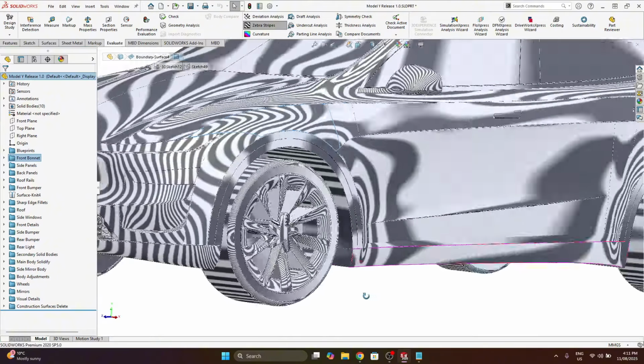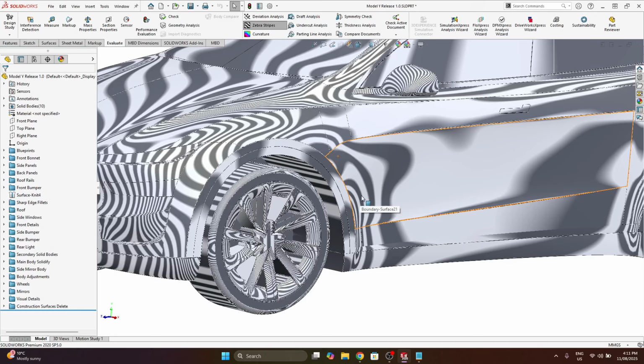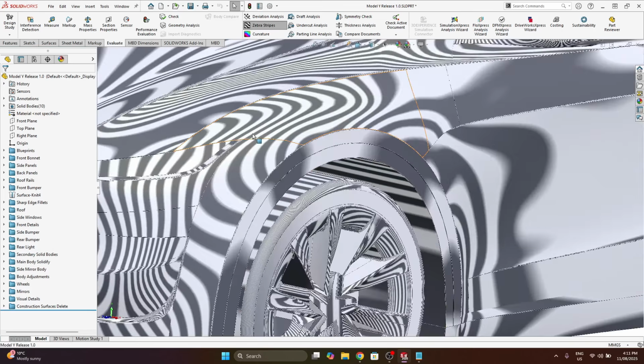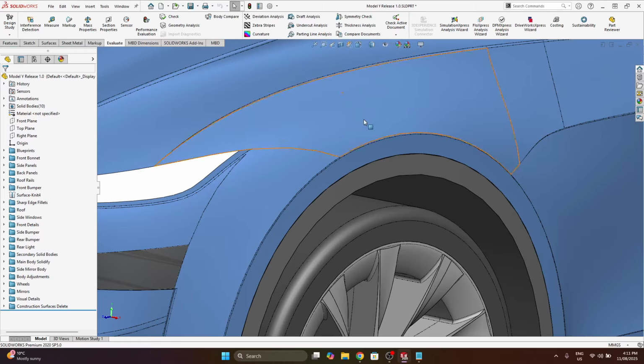This tangent continuity only really matters in certain manufacturing cases. For a car, we're going to have a glossy finish, so the way light reflects off the panels is important. I'm probably only going to 3D print this, so the way light reflects off is dominated by the roughness and surface finish of a 3D print, so it doesn't matter as much.